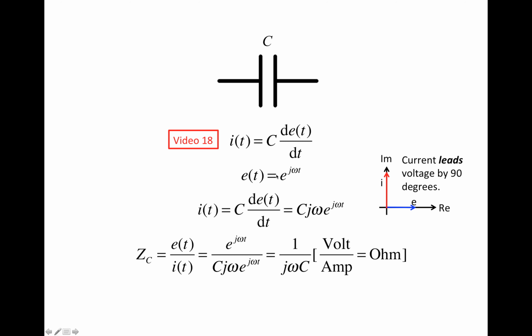So the sinusoidal function or the AC current or AC voltage associated with this particular complex exponential has an angular frequency of omega, right? So in the US, this angular frequency is going to be 60 Hertz multiplying 2 pi. Outside the US, this angular frequency is going to be 50 Hertz times 2 pi, right? So this kind of AC voltage is going to be either sine omega t or cosine omega t, and either of them can be expressed as a combination of these kind of complex exponentials. And in the last video, we talked about how to use these complex exponentials to represent those sines and cosines, right?